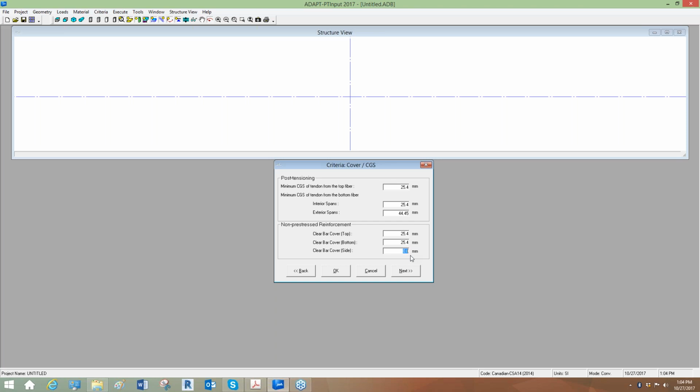It's meant for a requirement where the width of the beam gets reduced for one-way shear when the shear force is greater than some multiple of the shear capacity. So if you see this in ACI code, we're not doing anything with it in ACI currently. It is a placeholder for additional improvements we will make for deep beams later down the road for ACI. So that is the most noticeable input change in terms of the Canadian code.